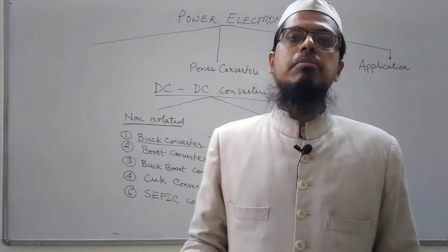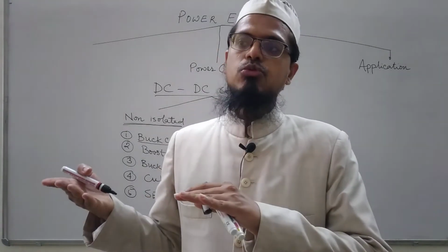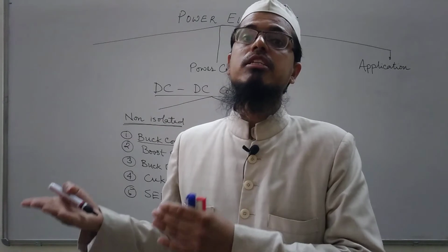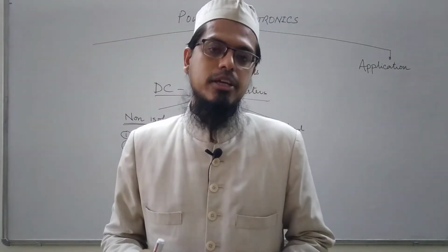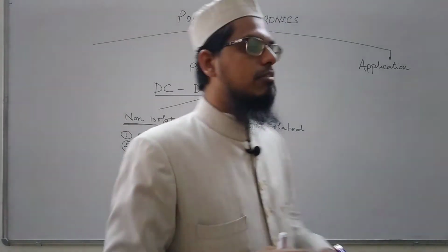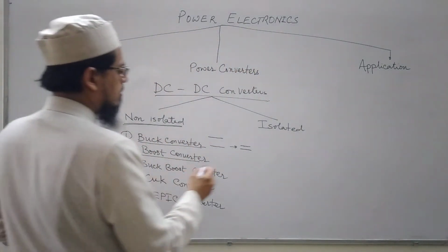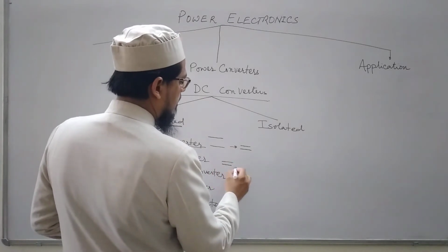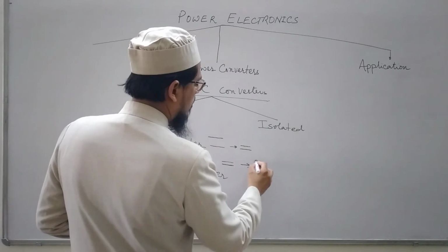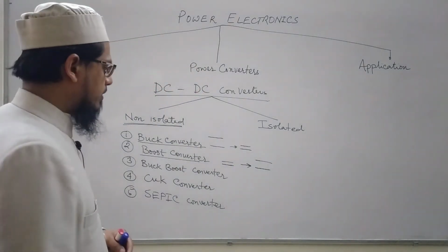That is done with the help of a buck converter, wherein the voltage level is reduced. Then again, there may be a case wherein the supply voltage of 12 volts is not sufficient to power a load which requires a higher DC supply. In that case, we have to go for the boost converters, which convert a lower DC voltage magnitude to a higher magnitude.